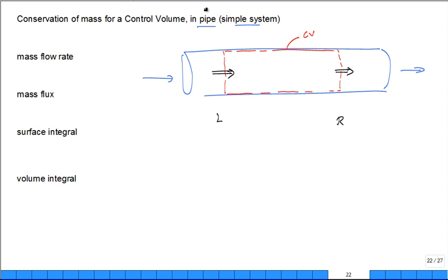From fluids, or from thermo, if you know the mass density, and if you know the average speed, U_avg, maybe you average coming this way down the pipe, and I know the cross-sectional area of the pipe. Maybe the pipe is diameter D, and the area is pi D squared over 4. Or if you know the radius r of the pipe, then it's pi r squared. But often in engineering, they don't quote the radius of the pipe. You say, give me a 2-inch pipe. Guess what the 2 inches is? Close to the inner diameter of the pipe.